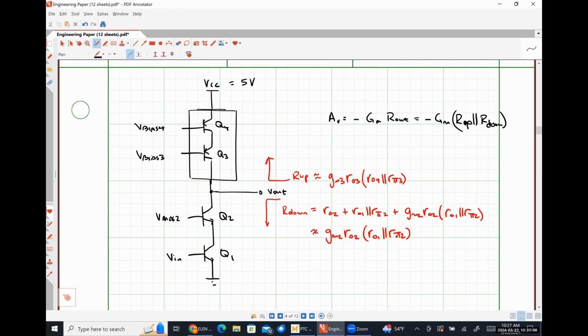If we put a physical resistor there, and let's say also, just for the sake of argument, that the current flowing down through here is on the order of half a milliampere, right? Or that's what we're trying to have happen to give us a good transconductance value, large value for R naught, all that kind of good stuff.